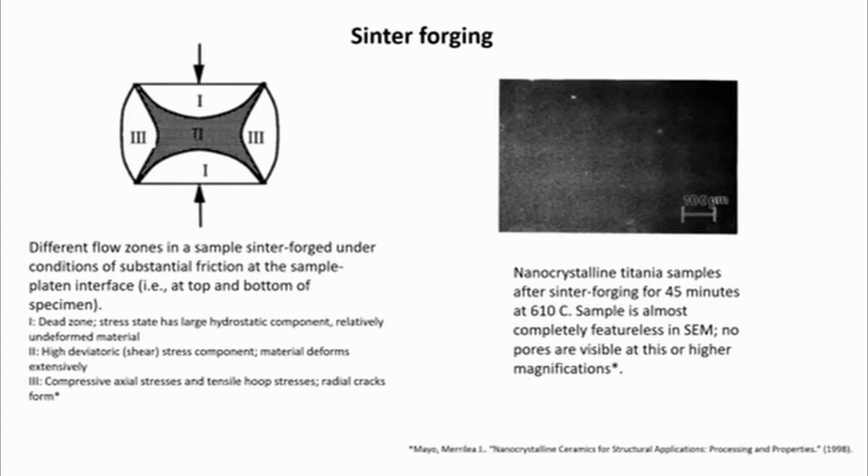Despite the advantage of being able to readily close large intergranular pores, sinter forging does offer some disadvantages. A significant one is the fact that the applied strain causes an additional type of grain growth, termed dynamic grain growth. In dynamic grain growth, the grains enlarge in direct proportion to the amount of applied strain. Thus, the very large strains needed to close pores also induce a correspondingly large degree of grain growth. A final difficulty with sinter forging is that die friction effects can prevent plastic strain, and hence densification, from being evenly distributed within the sample.